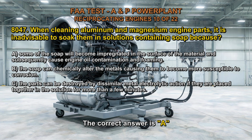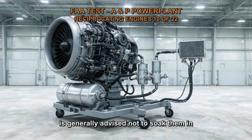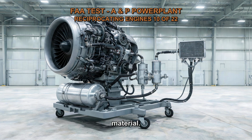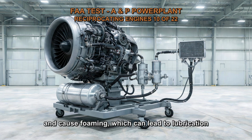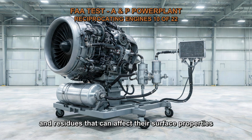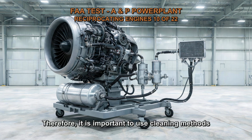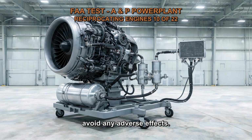The correct answer is A. When cleaning aluminum and magnesium engine parts, it is generally advised not to soak them in solutions containing soap. This is because soap can leave behind residue or become impregnated in the surface of the material. This residue can subsequently contaminate the engine oil and cause foaming, which can lead to lubrication issues and potential engine damage. Aluminum and magnesium are susceptible to certain chemicals and residues that can affect their surface properties and corrosion resistance. Therefore, it is important to use cleaning methods and solutions specifically designed for these metals to avoid any adverse effects.